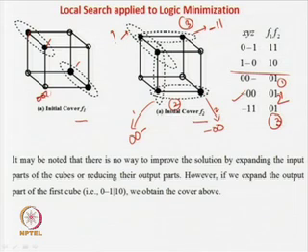Say for example, this is 0 0 0 and this is 0 0 1. So, how can you make a cluster between these two? Because the only difference is the last bit, 0 0 1. So, one bit is different, and you can actually make a cluster in between. That means you can eliminate one literal, and then this point will become this. You eliminate some literal from this one, and it will merge.